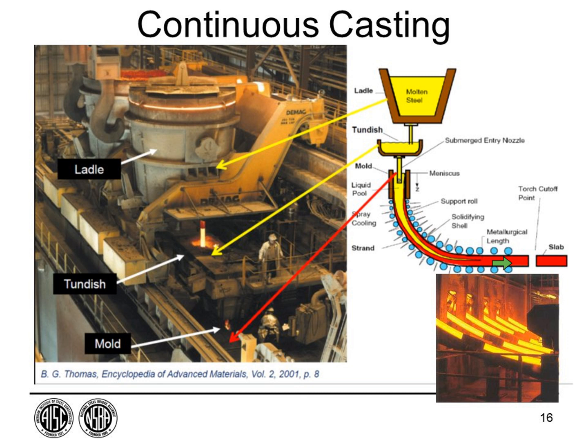So this is a continuous casting process. For example, if we're making wide flange shapes, they end up coming out looking like this, and they're called near net shapes. They look like almost an old I shape, very thick webs and thick flanges, which are then subsequently rolled to the final shape.